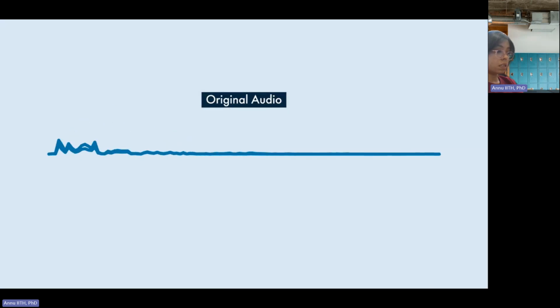As the filter gets applied to my audio, you can hear that the low frequencies remain while the high frequencies are eliminated, resulting in my voice now sounding rather muffled. When it comes to filter design, we're often concerned with the frequency characteristics of a signal, which can be hard to visualize and design in the time domain.